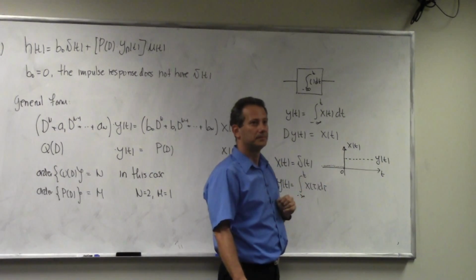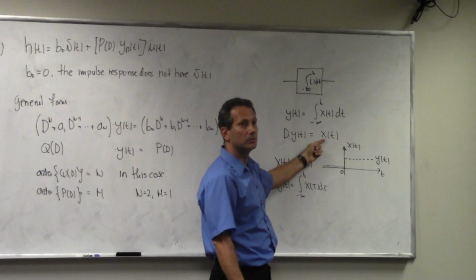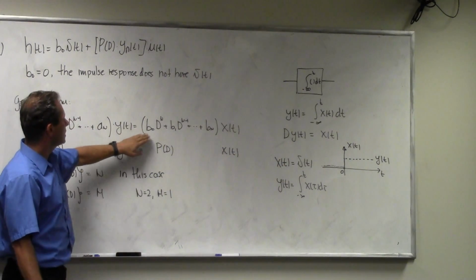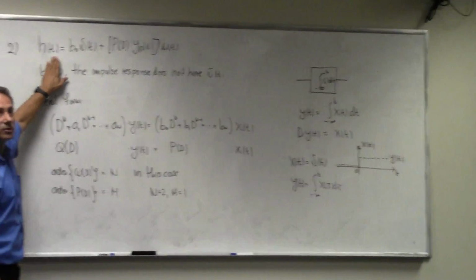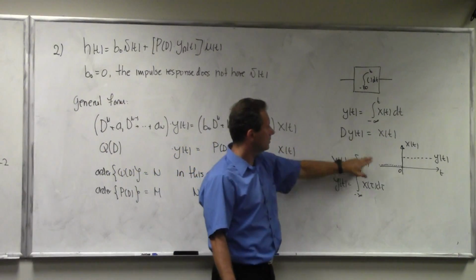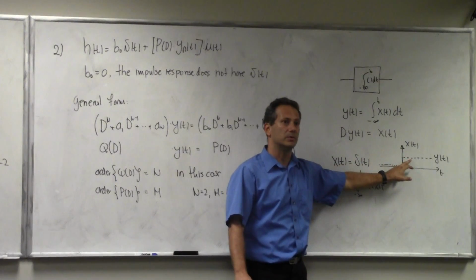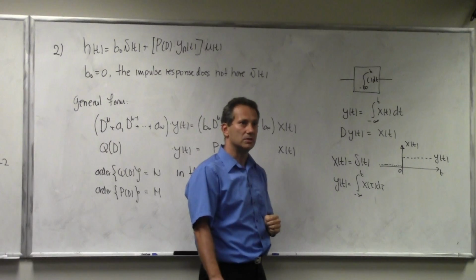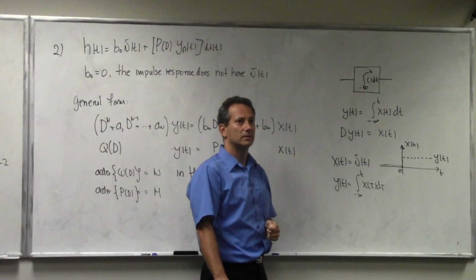Yeah, but this one up here is saying we didn't have an impulse on the input. This one we have an impulse on input. No, the one on the left, the B0 equals 0. Yeah, here we say this is an impulse response. So the impulse response of this system is just like the impulse response of this one. When presented with a delta pulse at the input, it will not have delta pulses in the output. It will have some step functions or possibly something that is discontinuous, but it will not go to delta. It will not go to infinity. Right?